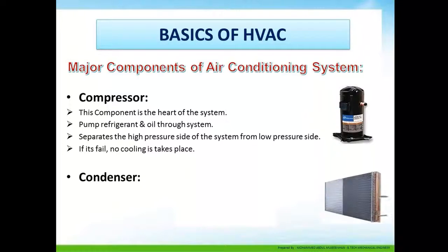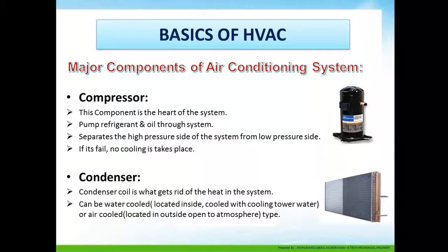Condenser. The condenser coil is what gets rid of the heat in the system. It can be water cooled, located inside and cooled with a cooling tower, or air cooled, located outside, open to the atmosphere. It traps dirt and requires preventive maintenance and cleaning.